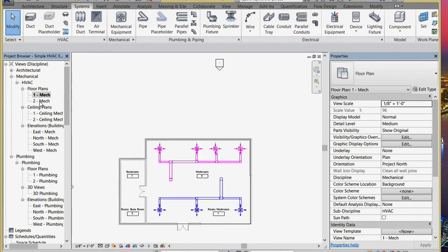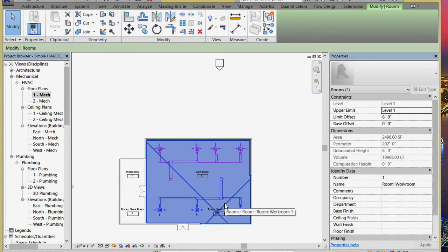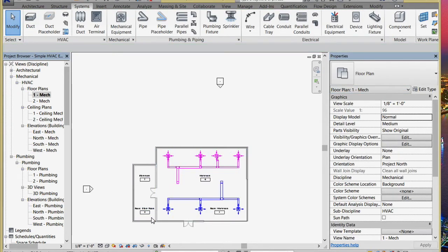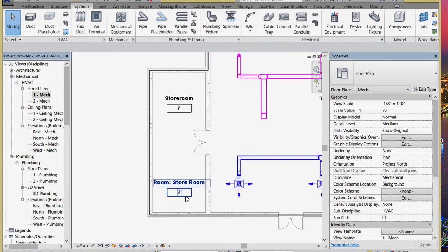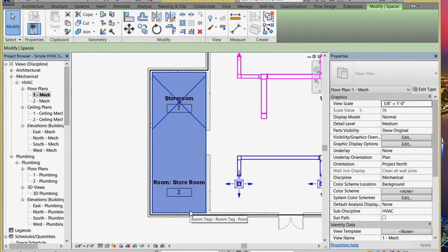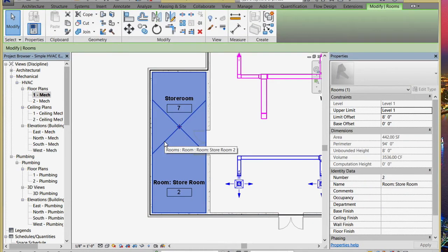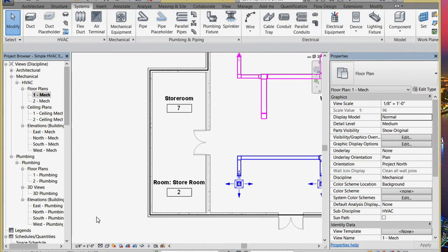And there may actually be a big overlap. In fact, what you'll see here is in my little space, I have a room. Go and make it like 10 feet tall also, just so it can be to the top. And I also have a room to match this space over here. And I think it's there. There it is. That's the space. There is the room. Again, I'm going to make it 10 feet tall, so it's sure to hit the roof. Otherwise, it'll be unenclosed. Okay, so now I have basically rooms matching the spaces and the real thermal properties.